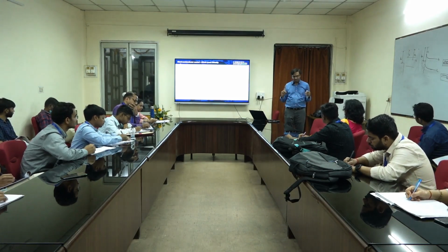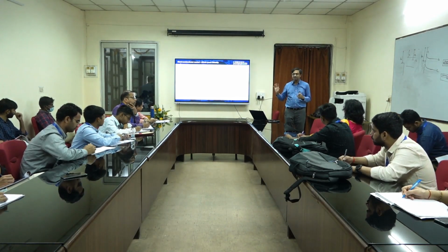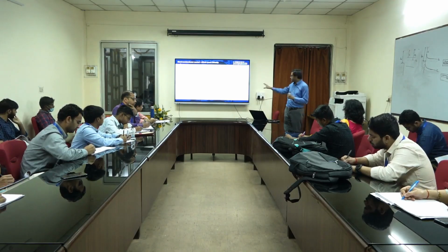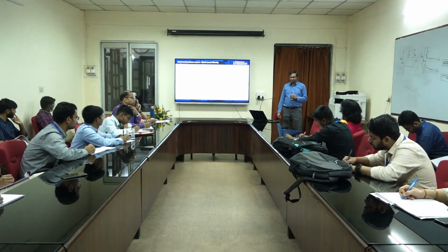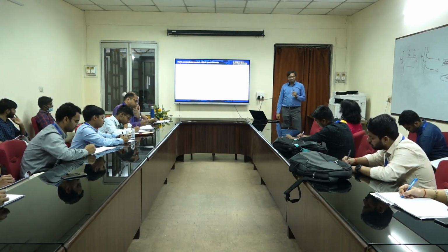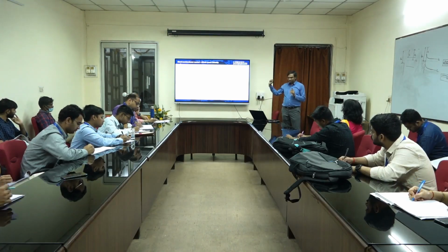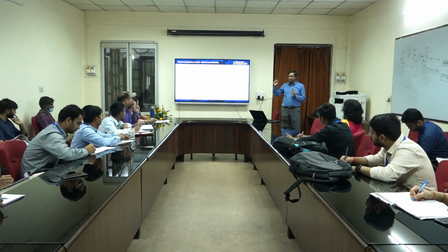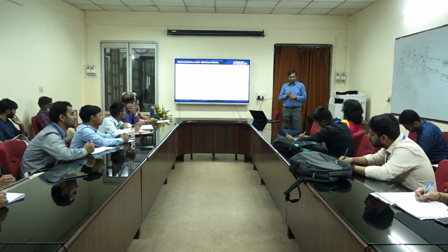Rule number 2: far away from the junction, the semiconductor remains the semiconductor, so the relative position of the conduction band, Fermi level, and valence band will remain the same. And then at the junction, the relative position of the conduction band of the semiconductor and the Fermi level of the metal should remain the same with respect to the vacuum level.